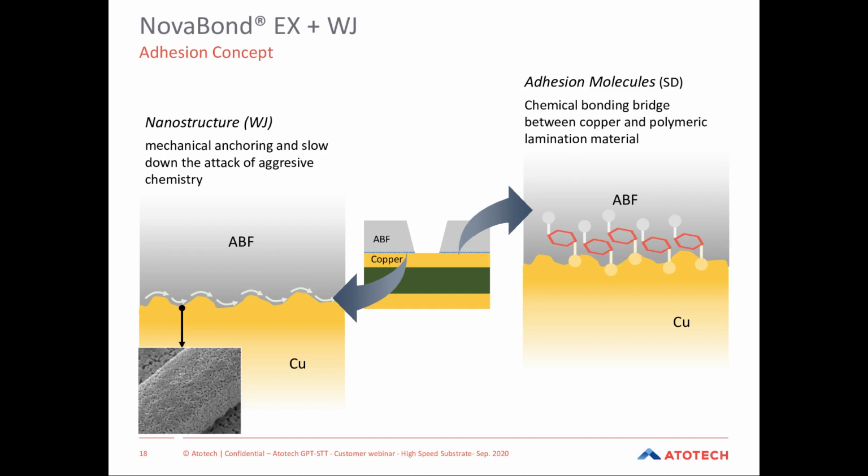After we create the nanostructure on the copper surface, there will be adhesion molecules, which contribute chemical adhesion as a bridge of chemical bonding between copper and ABF.